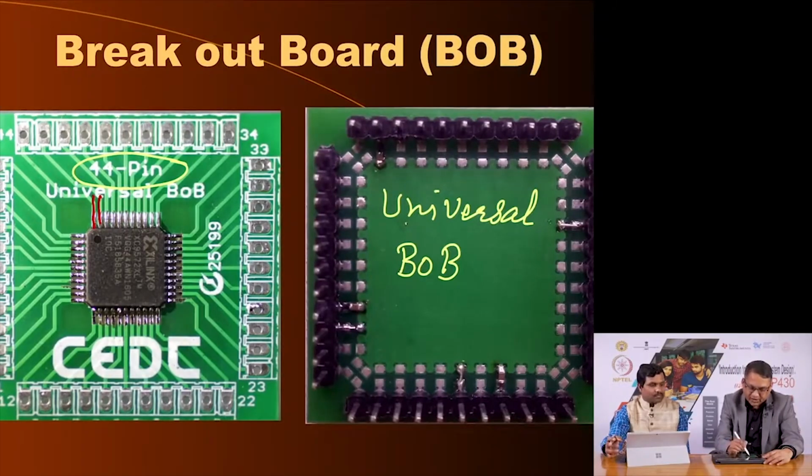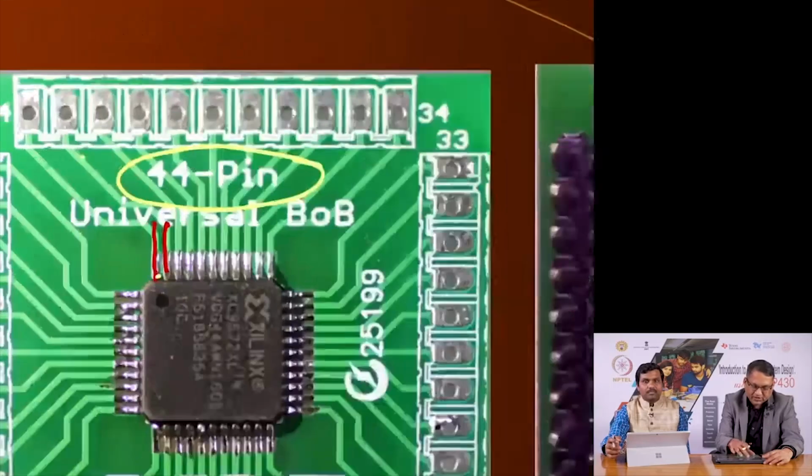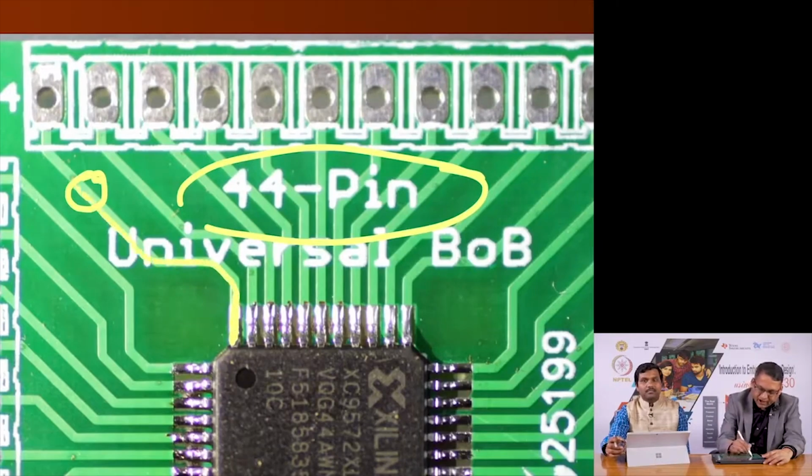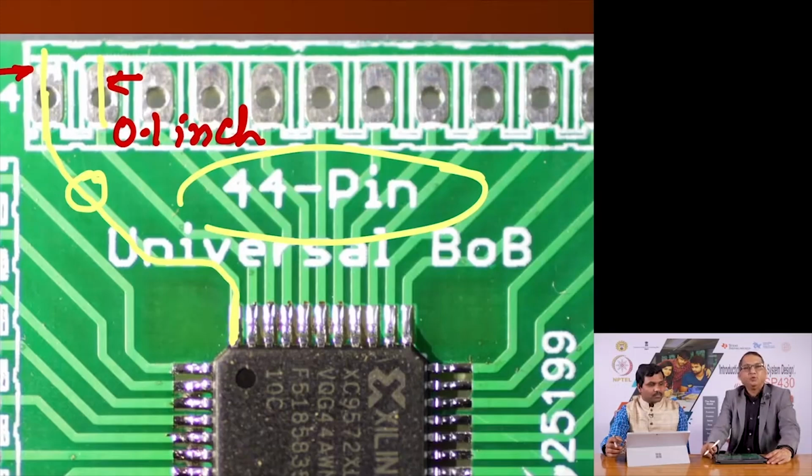Now, how do you make a universal breakout board? You see from each of the pads there is a copper track, as you see here. From this pad, the copper track is going here, to the next pin. These holes are placed at a pitch of 0.1 inch, which, as we mentioned earlier, is what the zero board allows you to insert components with. So, this solves that problem.